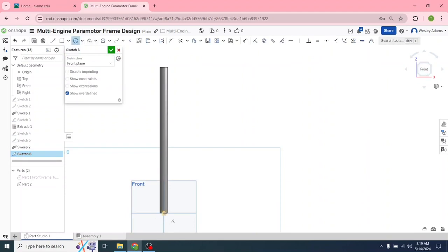Close that out. So let's go left click on sketch, left click on front plane, left click center point circle. Let's drag these away just a little bit. There we go. And then let's go create another one up here. Their size is not important yet. Let's left click on the dimension tool, left click on the outer edge. That's going to be 0.394 or 10 millimeters for that one. That's what we're going to use to mount these. We'll do the same thing here, 0.394.